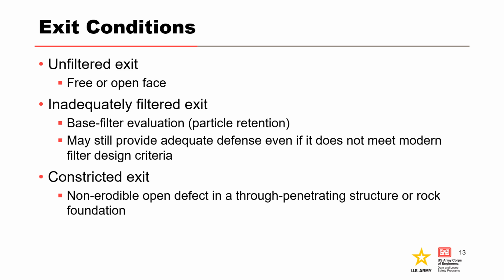When evaluating continuation, three types of exit conditions are generally considered. An unfiltered exit is a free or open face. An inadequately filtered exit may still provide adequate defense even if it doesn't meet modern filter design criteria. This requires an evaluation of the base filter compatibility for particle retention that we're going to discuss later. The last exit condition is a constricted exit, where the internal erosion occurs through a non-erodible open defect in a penetrating structure or rock foundation.